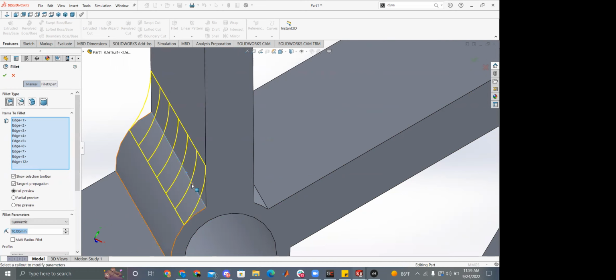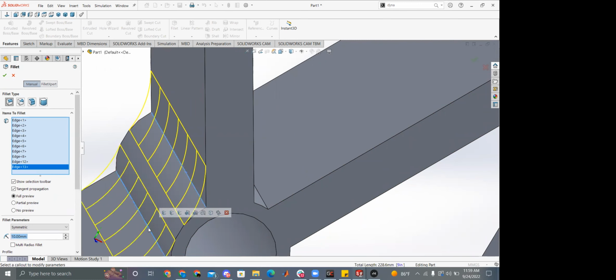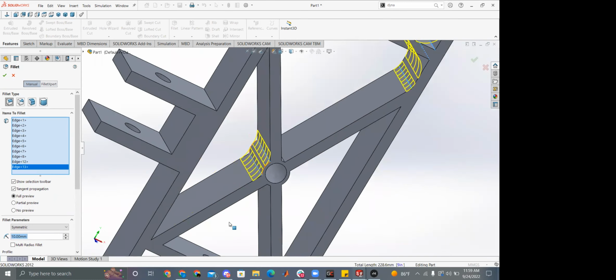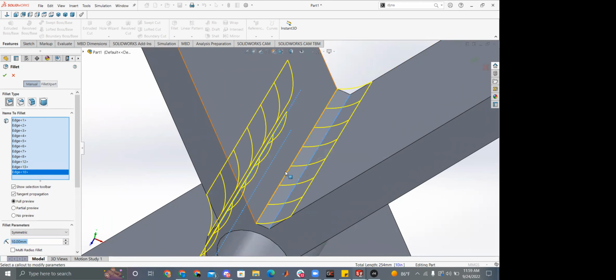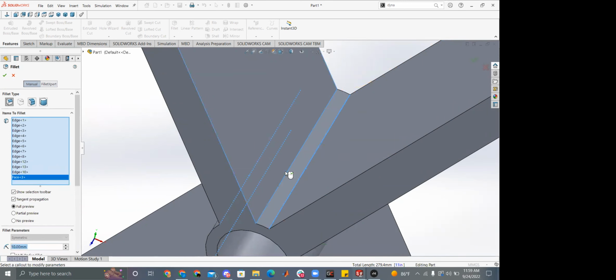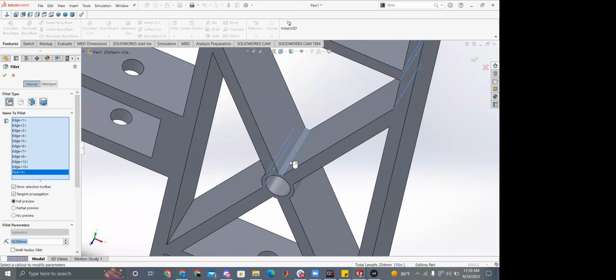You'll see it'll do the same thing on this one. A good way to tell if it's going to error out is you have these two lines selected, and you'll notice right there it's showing a preview. You select this one. Oh, why did it not do that before? Okay. On this one, if you select this, it'll show you a preview. Select this other one, it deletes both previews and there's nothing there. That's a good indication there's going to be an error there.